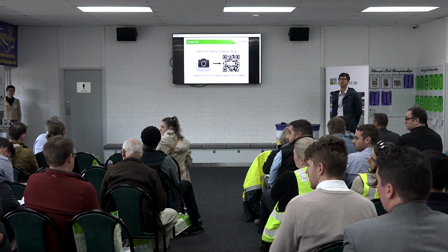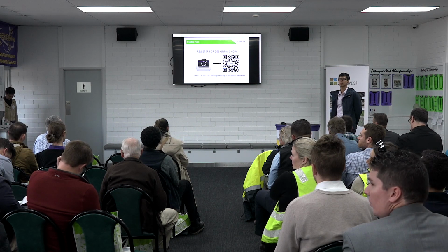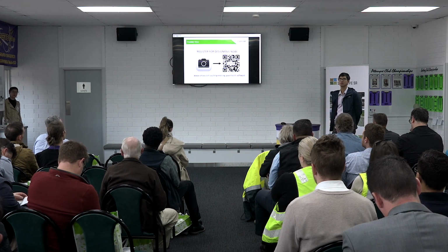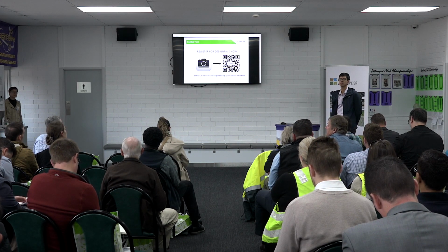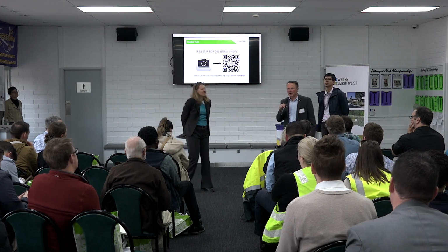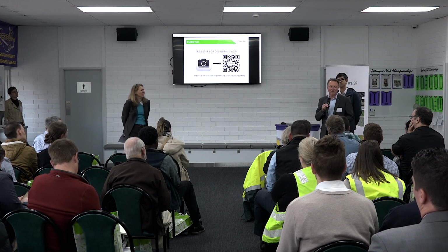Andreas Fusco, WGA. Is there any input or availability within the PERMPAVE software to take into account subgrade conditions for a soakage system? So if you're looking to use permeable pavers for soakage within your design, whether the subgrade material will be suitable? Soakage? I'm not quite sure about soakage. Might have to direct that question to Simon. Yeah. The only variable I think that goes into the software program is the hydraulic conductivity KS value of the subgrade, which tells you how fast it leaches down. So if you're looking for local soakage and you're actually holding onto it in the subgrade, which is not something I'd recommend, it wouldn't do that.